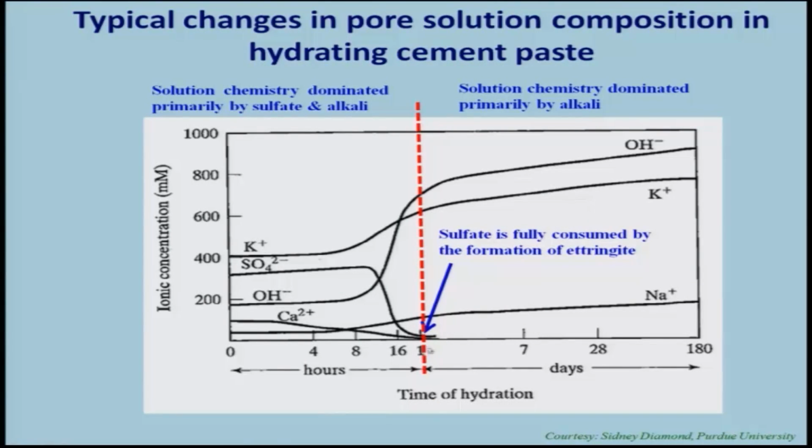Say approximately at 24 hours, the sulfate is fully consumed by the formation of ettringite or the reconversion from ettringite to monosulfoaluminate.